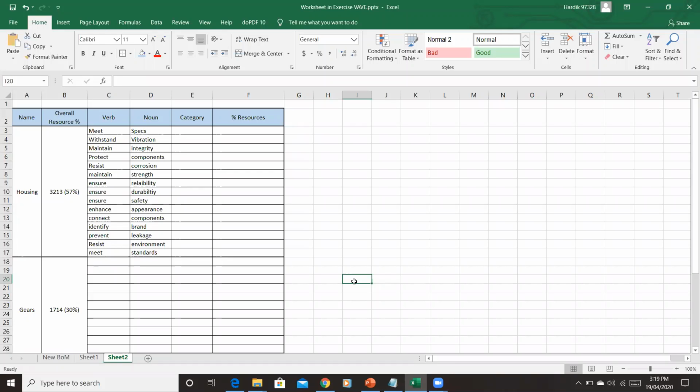But whether your supplier is giving you the warranty for the transmission or gears, or if any gears failed, and the complete transmission itself will fail. Or if any shafts, the supplier will give based on defect, because when we give them drawings, we give them standards: material standard, dimensional standard, chemical composition, all these we give, so that if they ensure all that, then there is no defect. Even the quality people set up norms. If it is a casting, what should be the size of the pores, how many pores should be there, all these details are already there in the standards. If they don't meet the standard, then only they are going to produce defective parts.